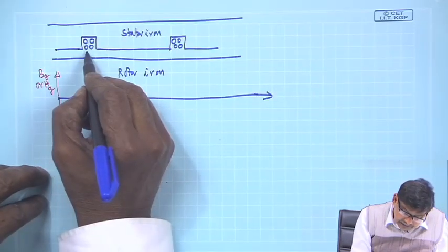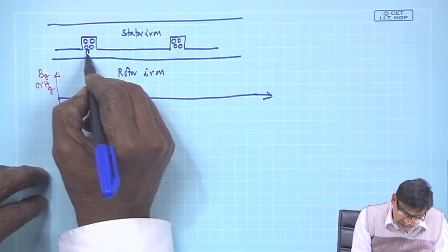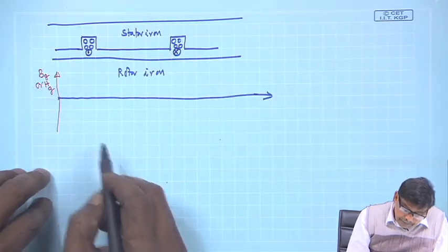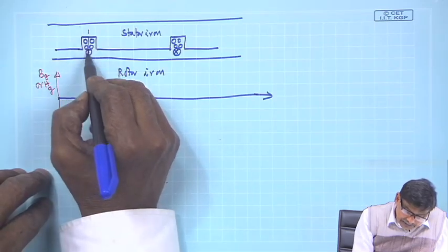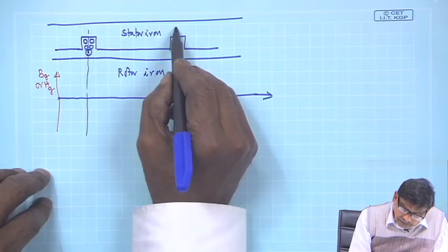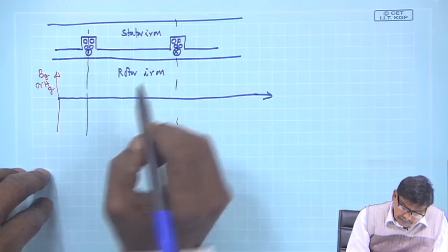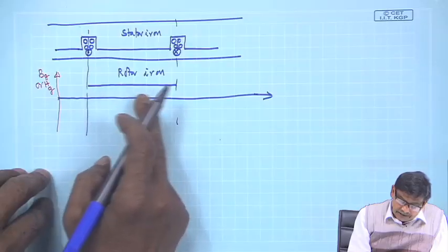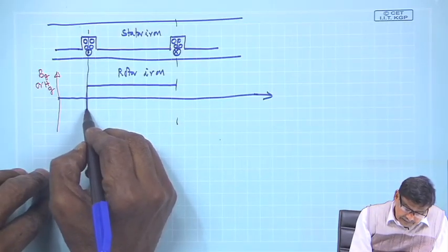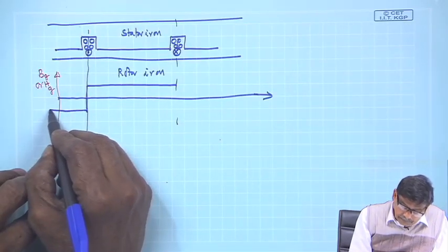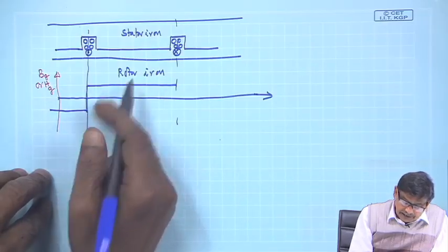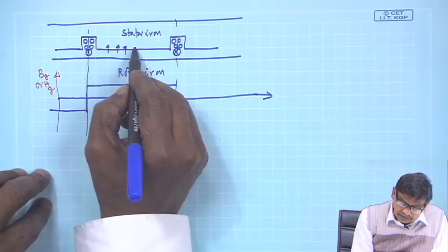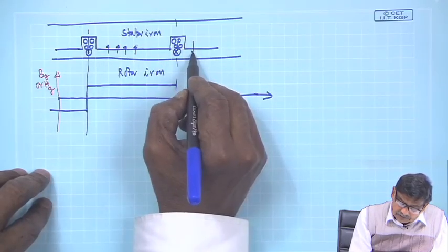Then if these conductors are carrying dot currents and these conductors are carrying cross currents, of constant magnitude, then at the center of these slots you draw two vertical lines, and between them it will remain constant, and it will switch over to negative sign, because lines of force here are like this, south poles, and here the lines of force will be like this.